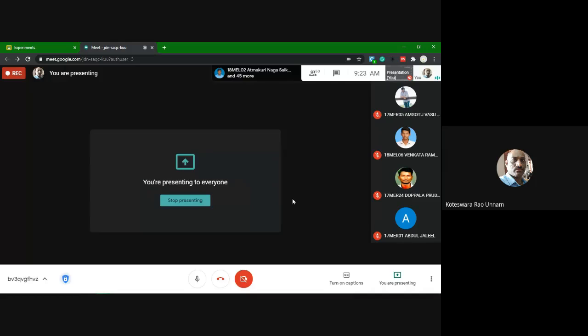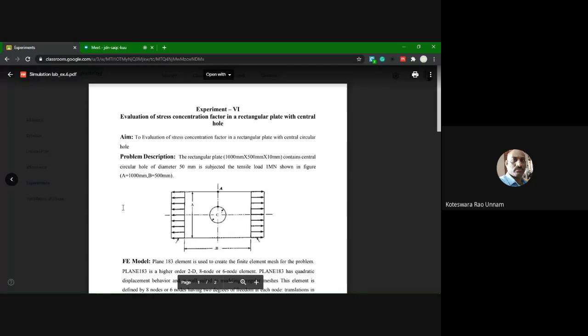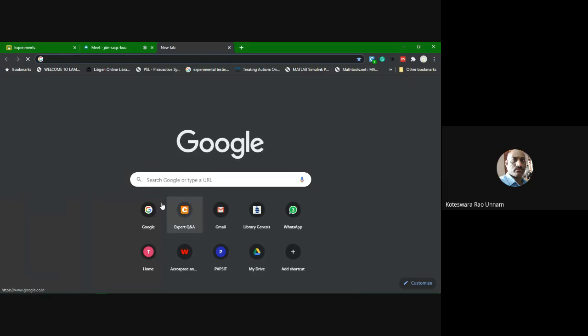From your course, design of machine members, you might have studied the stress concentration factor. If you look at that, the stress concentration factor is a function of the width of the plate and the diameter of this hole. It depends upon the dimensions of this plate also. Generally we consider the load line, whatever load we are applying, to be far away from this discontinuity. With those assumptions, you can easily find the stress concentration factor in a plate with a circular hole.